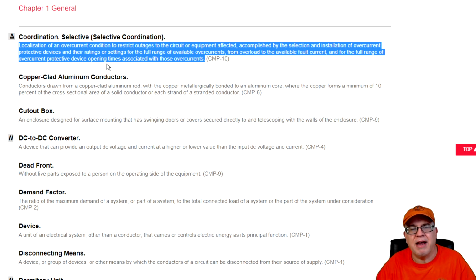So you have to design the system where it demands it in the National Electrical Code. Wherever it demands it, then I have to provide what's called selective coordination to that structure. Now, manufacturers, if you contact them and let them know, can provide you equipment that's already selectively coordinated. Or you can follow different types of trip curves from a manufacturer, or fuse characteristics, to create your selective coordination, but then usually you're going to have to prove it and show it.